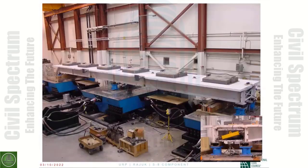This is here some series of the tests that we did on a steel plate girder bridge superstructure. I want you to pay attention. I don't know if you can see my cursor or not. I want you to pay attention to the end. These are the cross frames. As I told you before, if we allow them to buckle or yield, that will be a ductile element. If we don't allow them, that will be elastic.